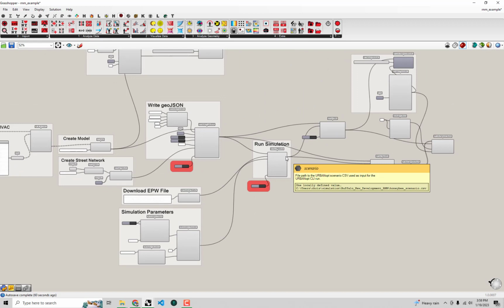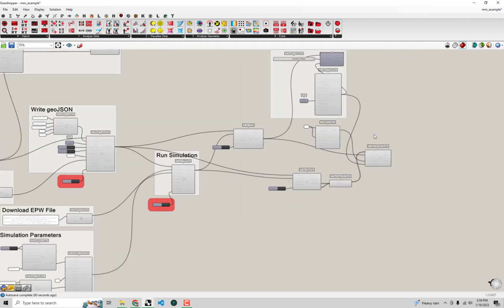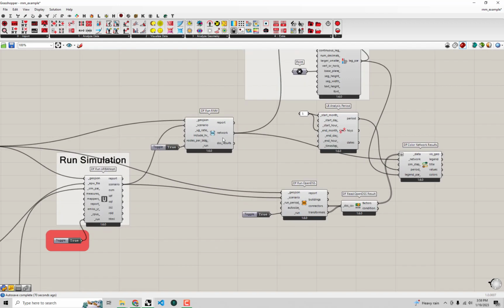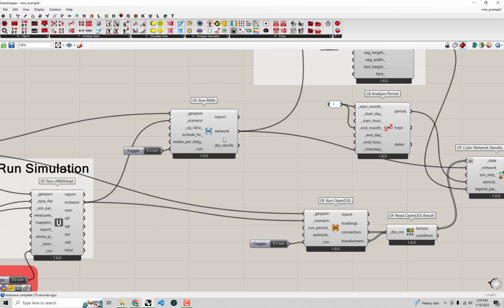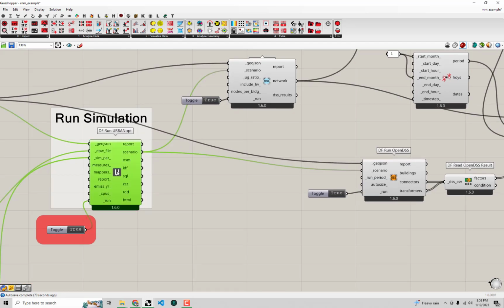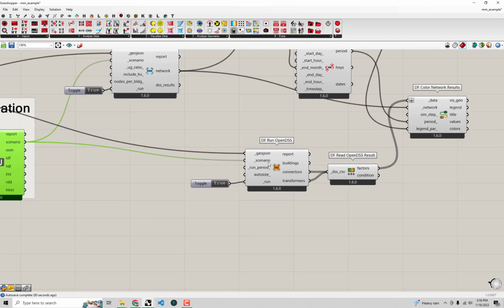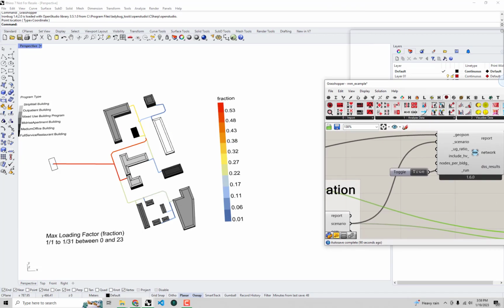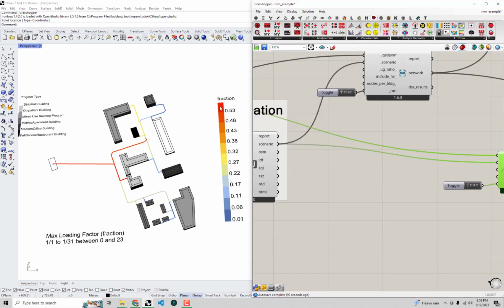And certainly over the next few years, a lot of that gas equipment and gas heating systems are going to be converted over to electric. So you can still use this RNM network that was generated using the electrical loads of the simulation with all these gas fuel boilers, but simulate power flow using a simulation with all electric air source heat pumps and electric service hot water and all of that. And you can start to see, I'm sure you'll get loading factors that are far above 1 at that point.